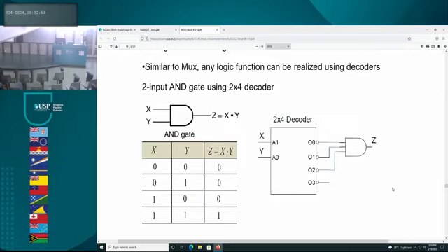Now, because there is a bubble, let us consider that scenario. If we select address 1, 1, x is 1, y is 1. What will happen to output 3? Now there is a bubble. Output 3 will be low, everything else will be high. All right, now, okay, so let us look at this particular thing. We do it such that you want to build an AND gate, right? So when input is 0, 0, which line will get selected?